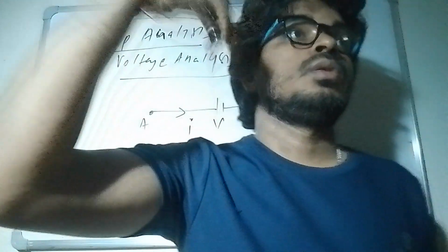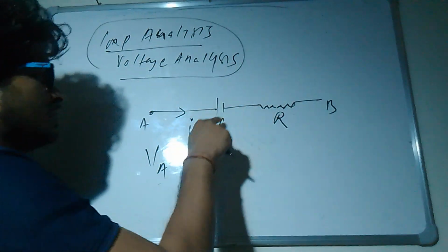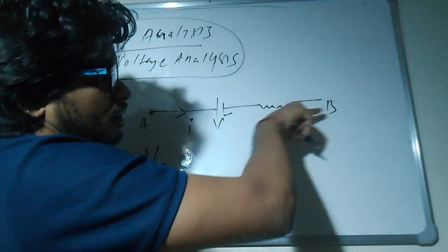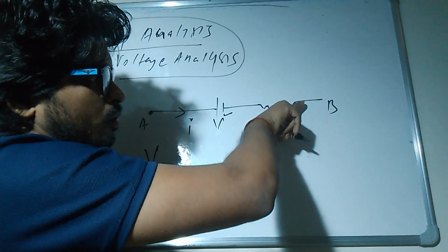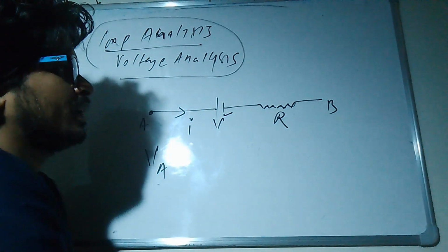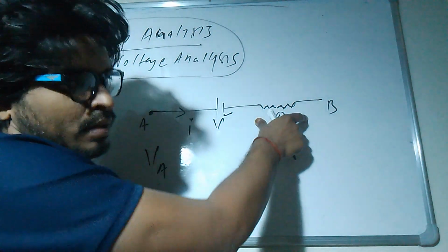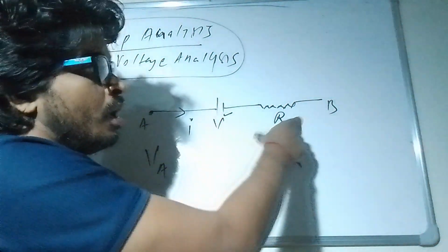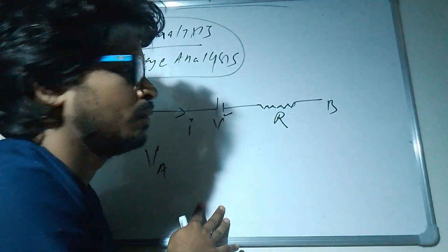Okay, so you have to change all the sign convention over there, but I am assuming all these things. If you take the second sign convention, second terminal, then in the direction of current flow, potential will decrease. So you have to write with a minus sign. In the direction of current flow, you write with a minus sign. In the opposite direction of current flow, you write with a plus sign.